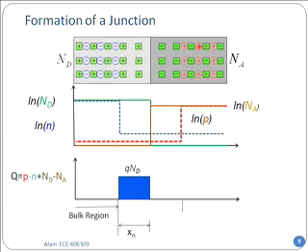And this time around, however, because of the sign, the net charge will be in the other direction. Do you see that? Because Na is negative, and I have depleted a bunch of holes close to the junction. So when I subtract, look at the net charge, it should go in the opposite direction. So that's it. After the charge exchange, this is the net charge I see in the junction, and that will govern everything about this diode. This little charge is going to govern this.